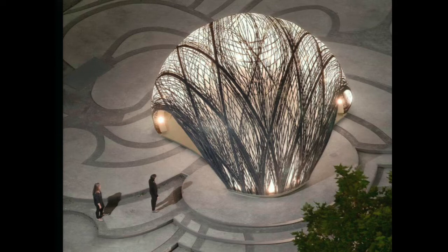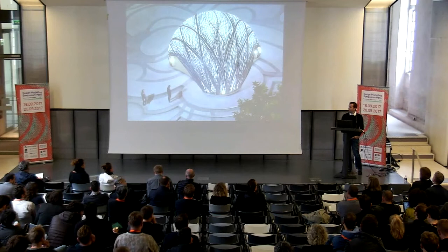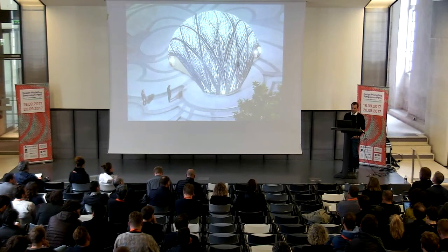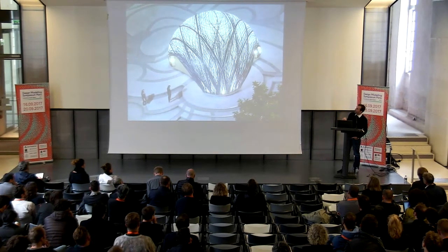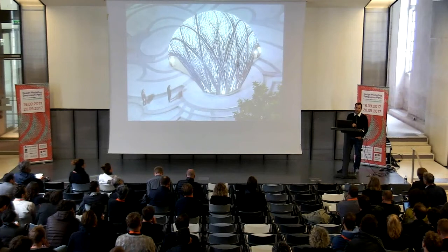What is interesting to me is that here we also collaborated with the Institute for Aircraft Design and Engineering at the University of Stuttgart, mainly on developing the pre-impregnated fibers. So the carbon fibers are actually frozen and pre-impregnated with the resin. But when we started the project, they considered that as being something that only uninformed people, to say diplomatically, would do. But in the end, we managed to build this entire structure with a diameter of 9 meters, 5 meters tall approximately, with a self-weight of 260 kilograms, which even in their value system is a pretty remarkable achievement.